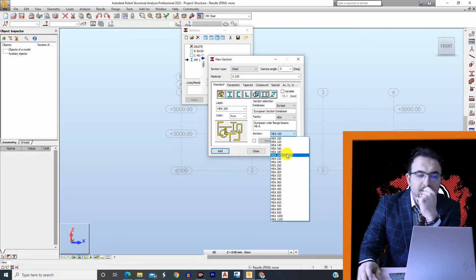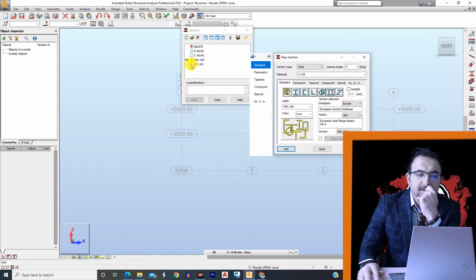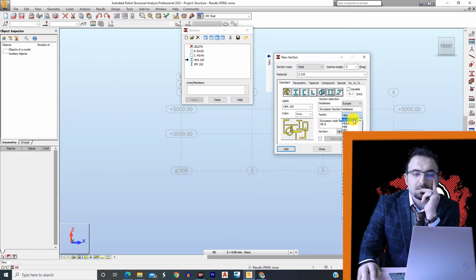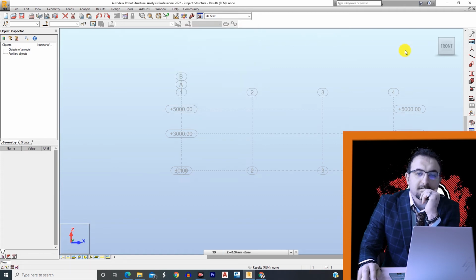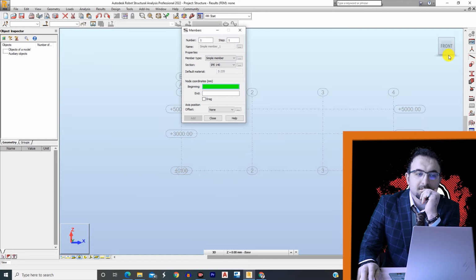I will choose 100, just 100. I see it is added here, and I can choose, for example, to change HEA for HEB 140. Close. I can delete this profile, yes. So I'm good, I can start drawing.